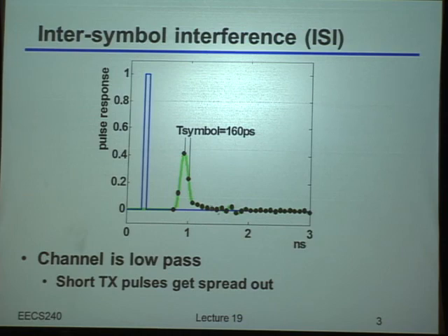All of the samples you get after that time are considered to be the post-cursor, and all of the samples before it are the so-called precursor. So the cursor is just a reference point. But usually when you're asking about when you would sample your data, you'd try and sample it here, right? Because most of the information about that data is showing up at that particular time instance.